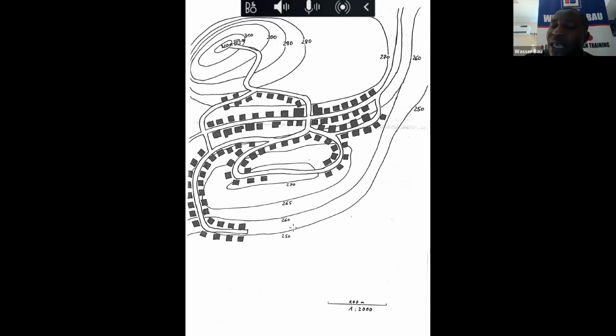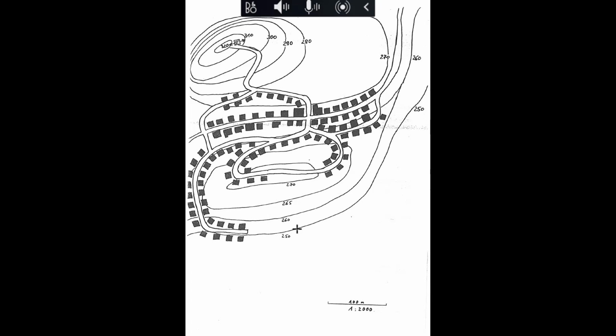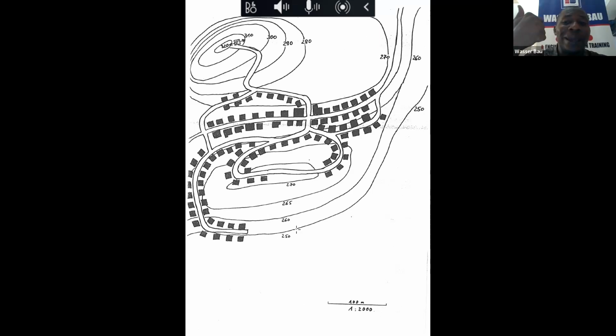And here we have a geodetic height of 60 meters, which, by rule of thumb, translates to about 6 bars. So this is cool; we are good to go. It means the maximum pressure anybody can get, not minding losses, is 6 bars.